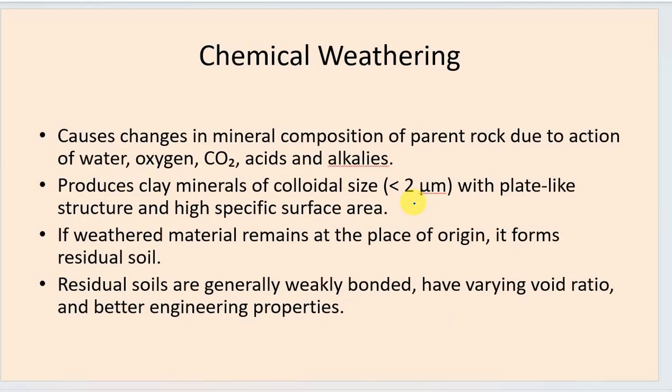Next comes chemical weathering. In chemical weathering, the mineral composition of rocks changes due to chemical reactions caused by water, oxygen, carbon dioxide, acids, and alkalis. This process produces very fine particles known as clay minerals, generally smaller than 2 micron in size.